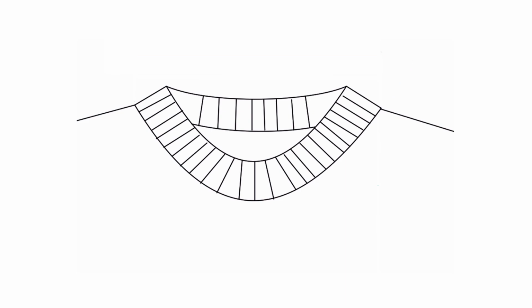Because of the stretchability in the knitted fabric, the edge-to-edge measurement may not be consistent, which often poses a problem, not only for the manufacturer, but for the quality inspector too. In case the neck measurement is provided edge-to-edge, and not seam to seam, it is difficult to calculate where the seam shall be placed, because the edge so formed at the neck is not straight, but is always at an angle.